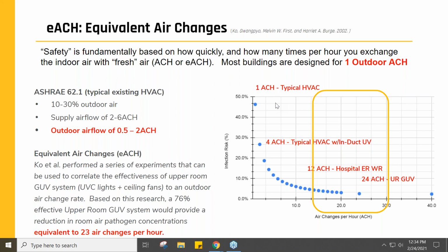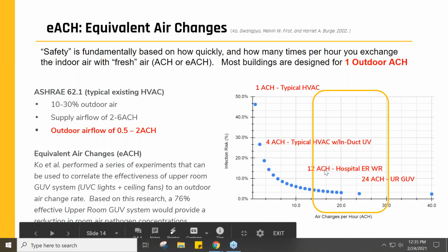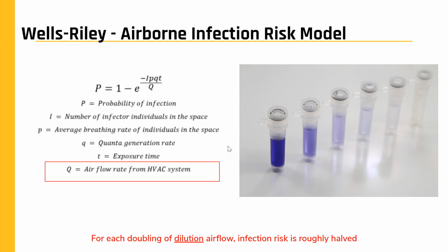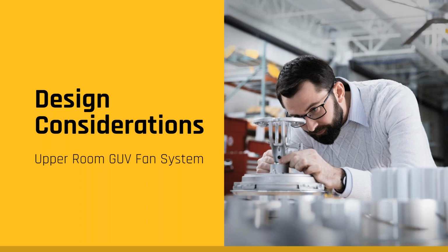If I think that portable air filtration device can capture all of the air volume in every corner of the room, floor to ceiling, not just the air local to the machine, and through the technology of that machine I can achieve 12 ACH, or 12 eACH, then I would tell that person that might be a good option. You're delivering the ACH that you want to make the space significantly safer. So I'm offering this to you as not just a Big Ass Fans measure of performance, but to help your customers understand that ACH is a very easy to understand universal measuring stick for comparing various investments.